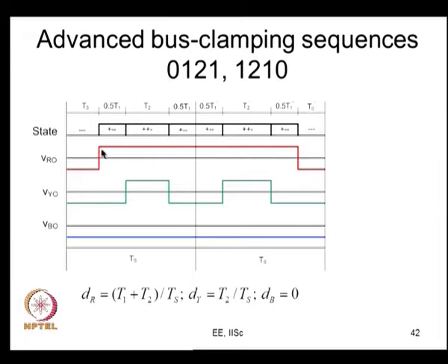The switching energy lost is ER plus 2 EY, because the Y phase current is not going to be significantly different between this instant and that instant. ER is a function of IR, EY is a function of IY. So, it is ER plus 2 EY, the energy lost in the sub cycle, EB is equal to 0. Is it good, is it not, does it have any advantage or disadvantage?